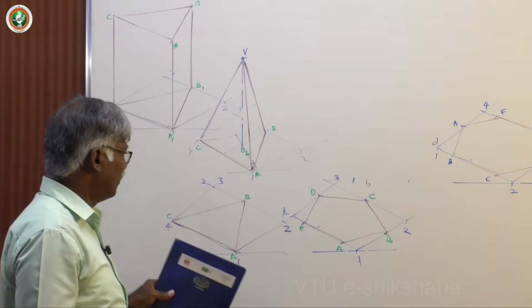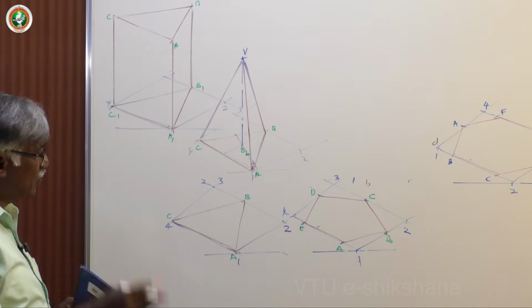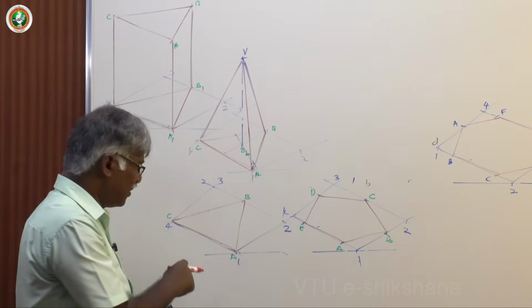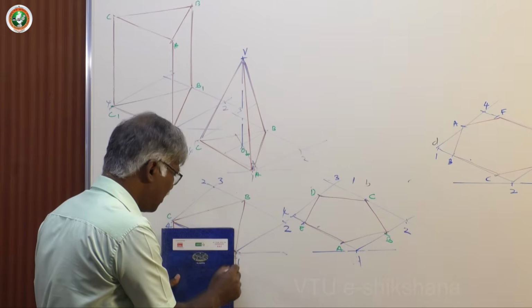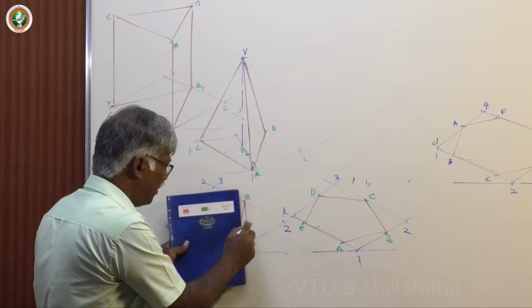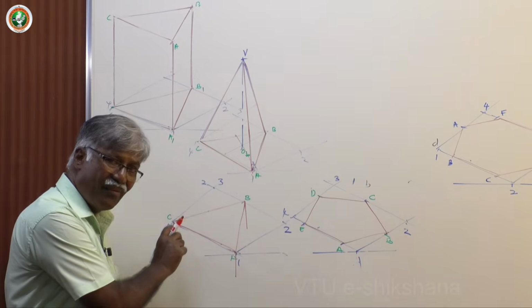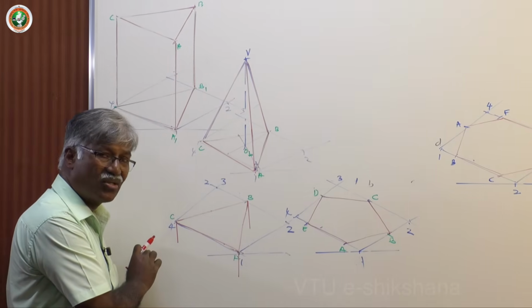Okay, now the block. How to create a block? As we discussed in the square shape, first draw the top face. Draw only the lines which are visible. So now I have 15 mm thickness, say a 15 mm thick block.